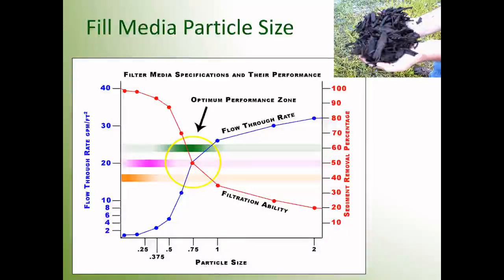And then you also see it acting more like a filtration device. And as those particle sizes get smaller and smaller, you reduce pore spaces basically down to zero, and what you have is a solid barrier or a dam or something that just restricts flow. And so it can work quite well in low flow environments or where just flow restriction is all you need, but they will quickly go into bypass through overflow or end-around flow type situations. So you see some that are specifically designed for this, and others that are specifically designed for high flow and also filtration mechanisms.